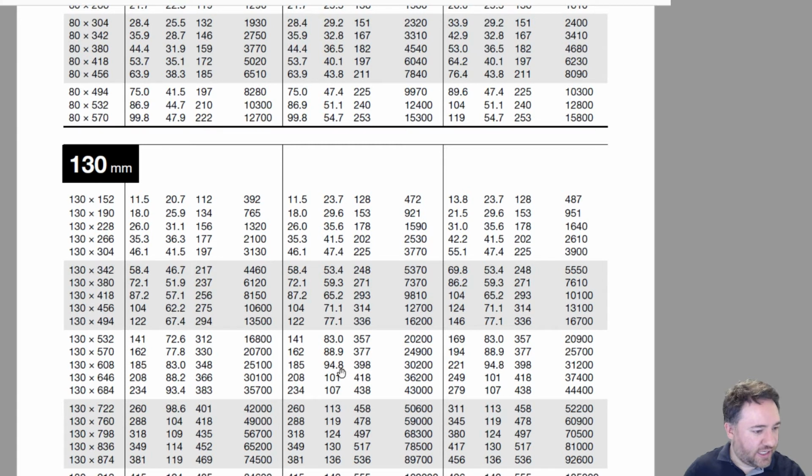Even though it's right on the edge? Because I have some ways to juice this number a little bit, which we saw before. So this is the simplified shear calculation. I know that I have some options to get a higher effective shear resistance. For example, I can look at my VF at d from the support instead of looking at VF at the support.